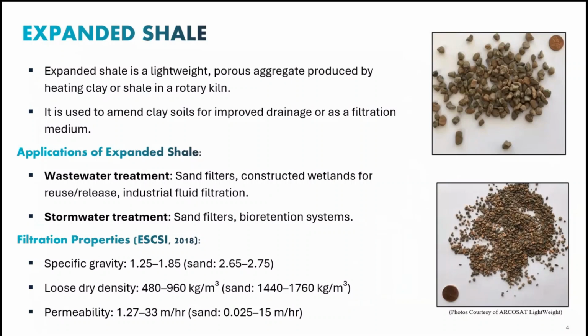So expanded shale is nothing but clay. We heat up the clay at very high temperature and make it something very light and porous, some sort of granule material that is very light. In this picture on the top, you can see the gravel size of expanded shale. On the bottom, you can see the sand size of the expanded shale.